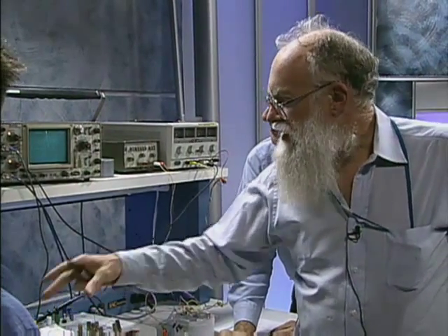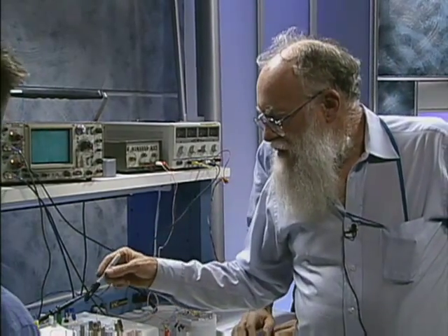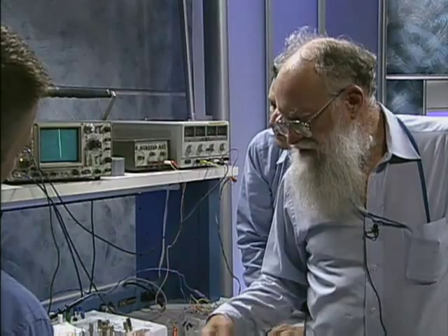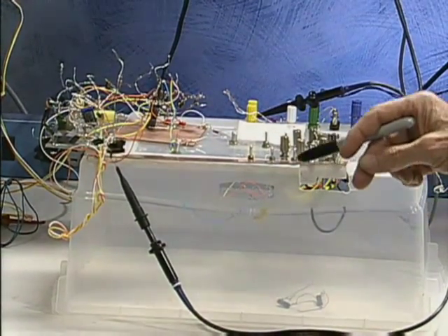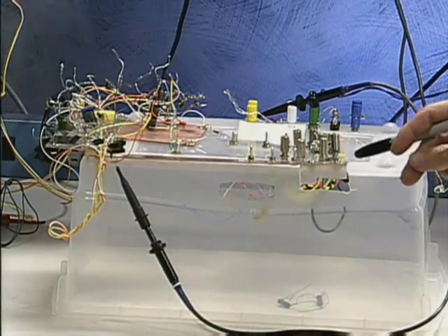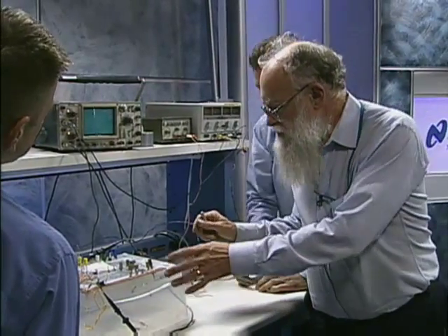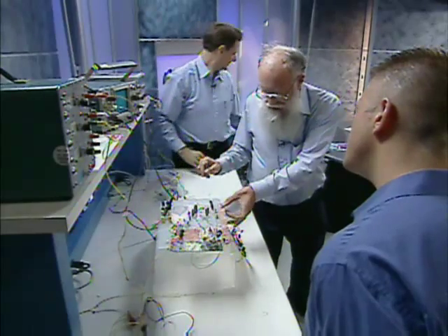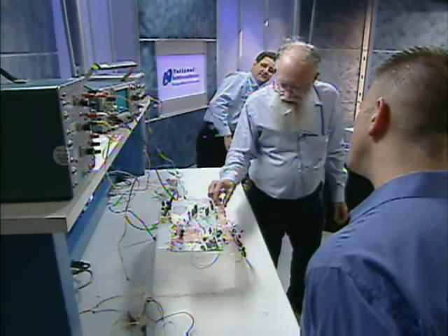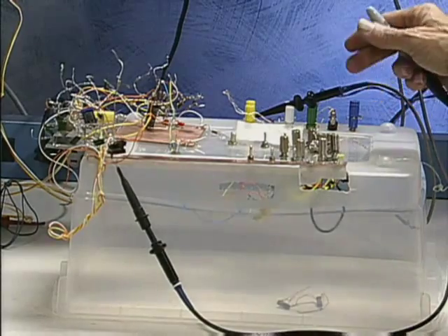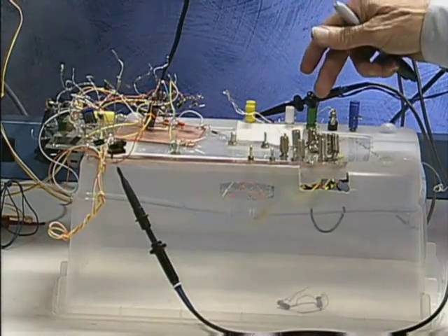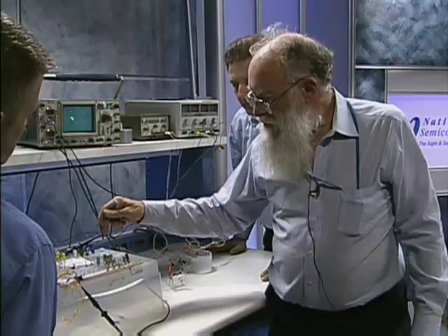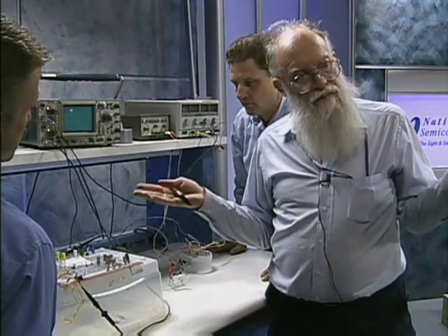Anyhow, so these shunts, we have precision resistors inside here. This is a Rubbermaid box. I measured this thing at the million megohm level. It has no errors. Polyethylene's pretty good. I moved this around to have this give no effect, because this swings out, so I can put any purchased precision 0.1% 1 milliohm resistor. Why do people need a milliohm?